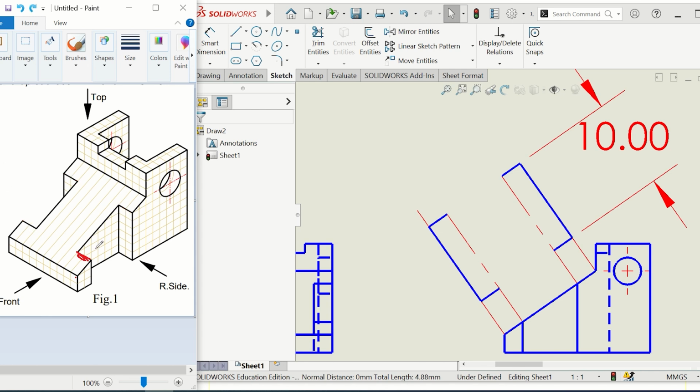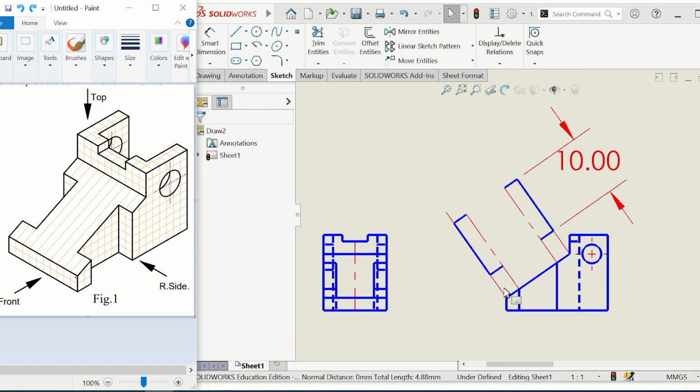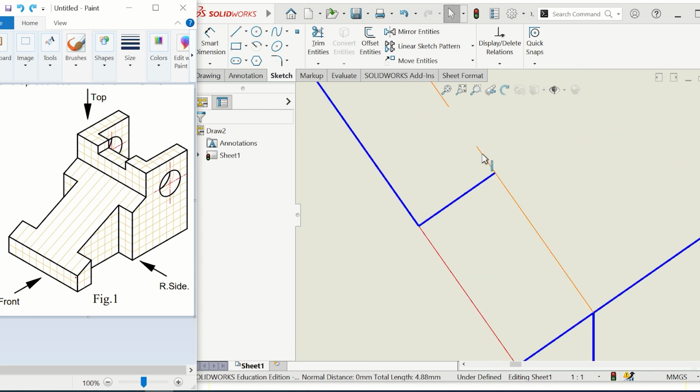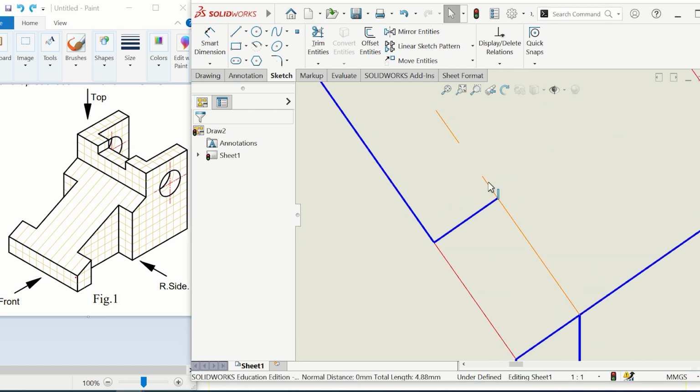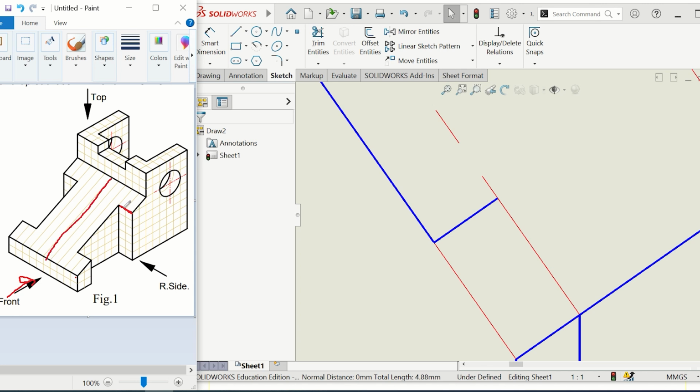Okay, how do I draw them? These lines are going to appear like this, along the red line here, along the construction line here, and having a length of what? Of 2 units. This distance of 2 is not distorted when I look from the front. It remains 2. The distorted distances are along this direction, not along this direction. Along this direction, all the lines remain what they really are. They are not projected, actually.